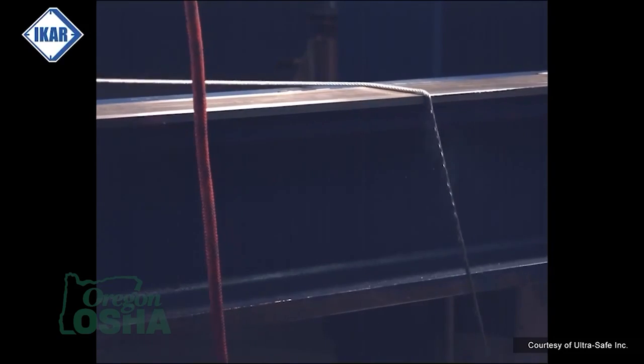The reason for that is when we fall over a leading edge, we create a point of friction. We've got that pinch point that's there. If our energy absorber is above that leading edge towards our anchor point, where that point of friction has happened, our energy is not going to transfer up to that anchor point or to where that shock pack potentially could be. It's not going to be controlled and decelerated down to an acceptable level, either the 1,800 pounds or 900 pound average by ANSI, and the worker could be subjected to higher arresting forces or fall forces there.